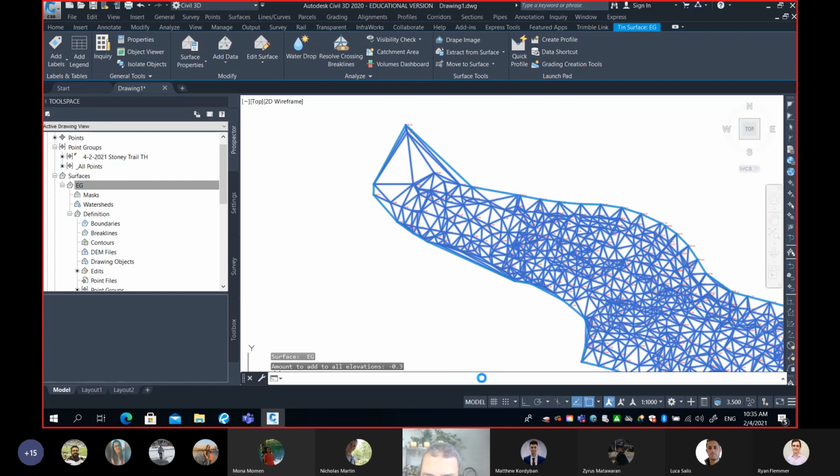If you guys remember total station, we use a rod. We use a rod, and at the bottom of the rod there is a wedge. It's very hard to visualize right now because I have no photo, but at the tip of the rod there is a wedge, and this wedge you can disassemble. You can take it away. In general, when you read a reading on the rod of 1.35, it is calibrated to measure from the tip of the wedge.